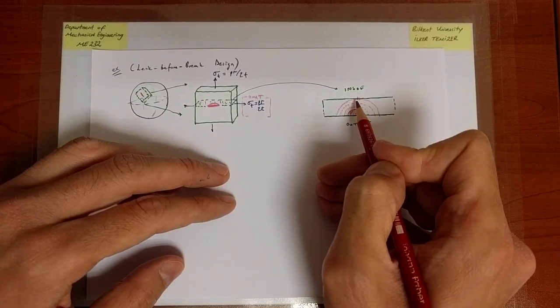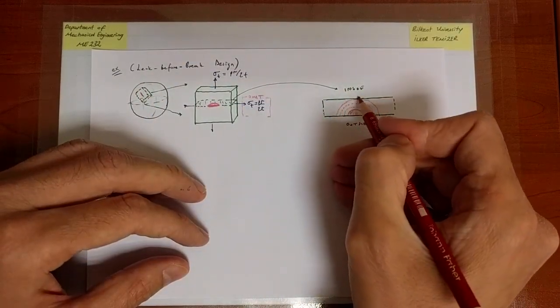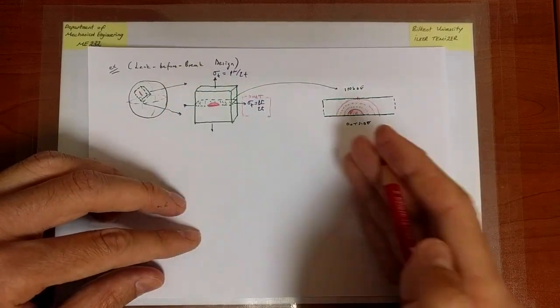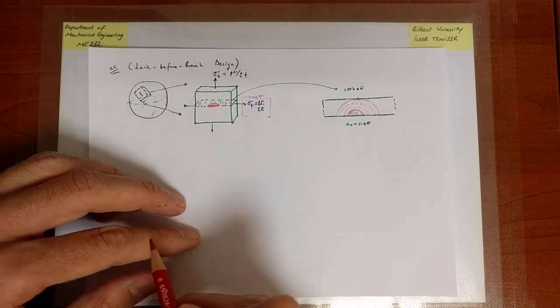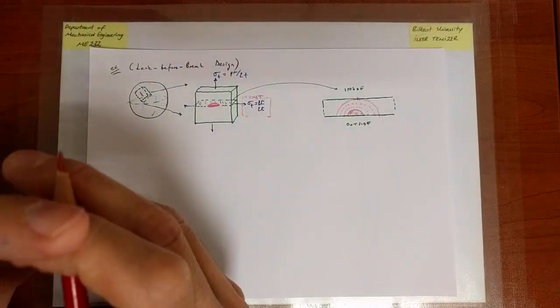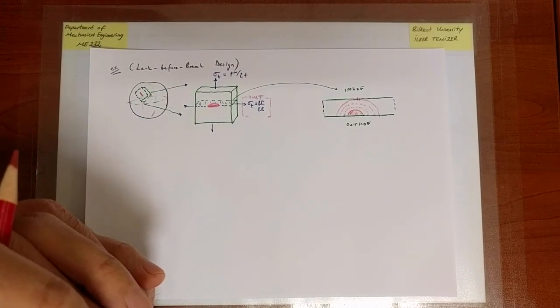And when that happens, the vessel is unpressurized, and although the crack is large, the stress intensity factor will go to 0 because the gross stress will be 0 because the pressure is removed. Gross stress has to do with P. So when the gas leaks, the vessel will be unpressurized, it leaks, and you are not going to face fracture.